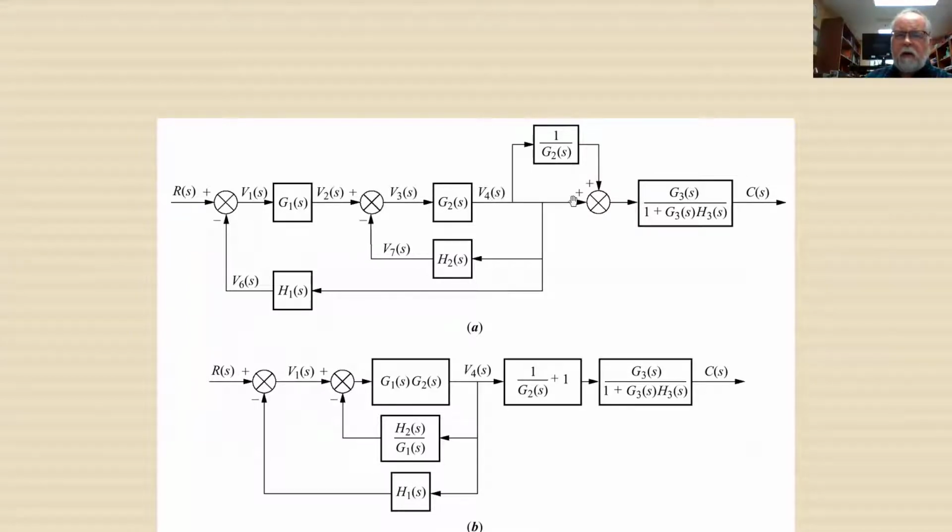So we know from here going into this function block, I've got two paths, that path and the path going up. And so I can replace those two with this one block. Now that I've got those two things going into the summing junction, I don't have to have the summing junction anymore. Okay, so this transfer function here is that summing junction.